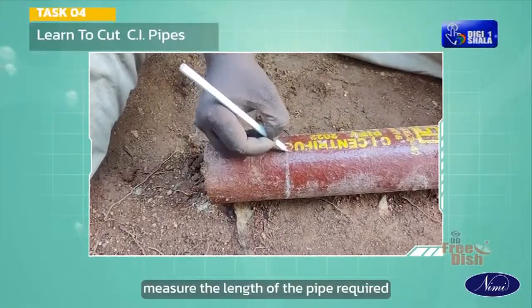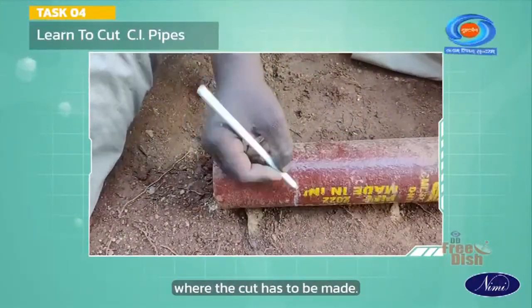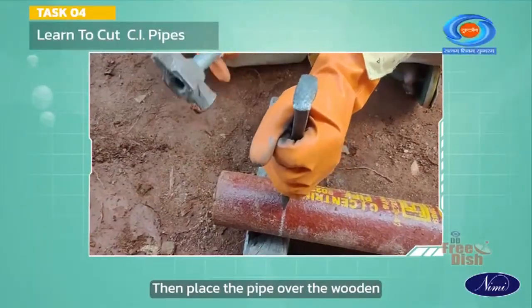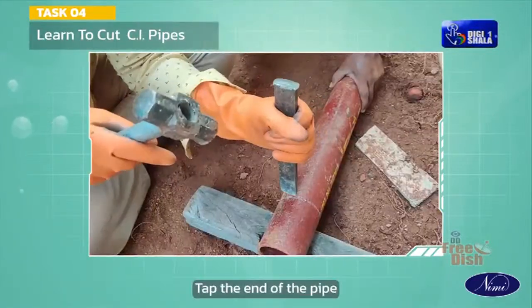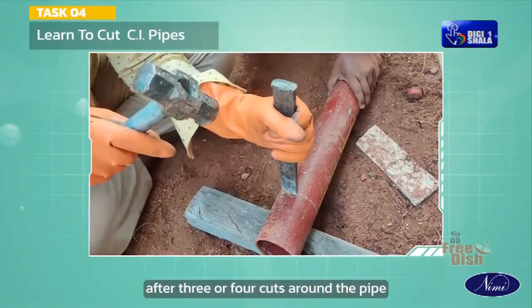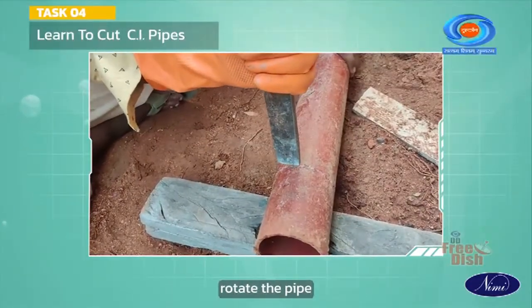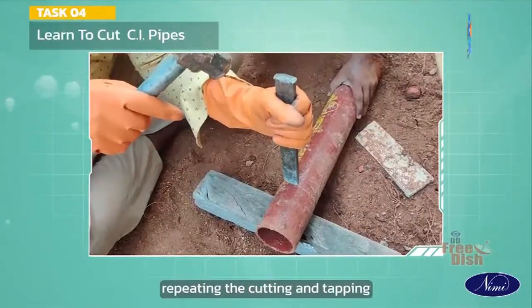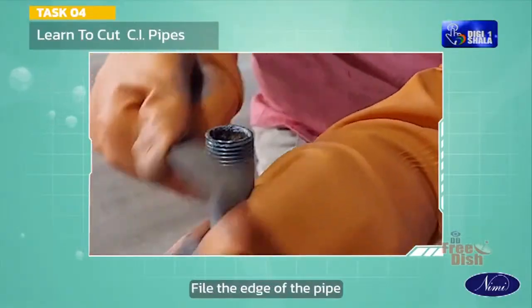Measure the length of the pipe required and make a mark around the pipe where the cut has to be made. Then place the pipe over the wooden V block and cut the pipe along the mark. Tap the end of the pipe after 3 or 4 cuts around the pipe. In case the pipe does not break, rotate the pipe, repeating the cutting and tapping until the pipe is cut. File the edge of the pipe with a flat file.